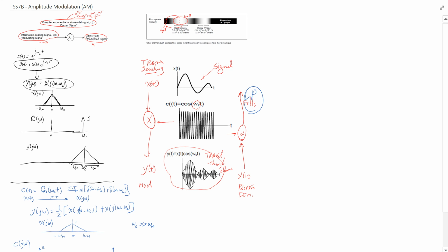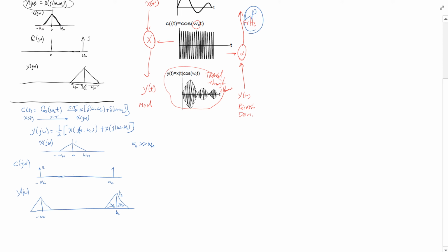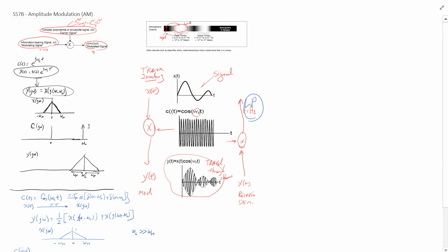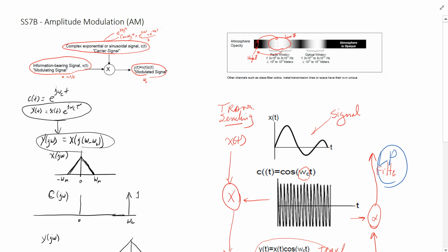The goal is to take a frequency and move it in the frequency spectrum to where it's going to go through. For example, for an AM station, a human voice is being transmitted, music and things like that. That's 20 kilohertz. So they take that 0 to 20 kilohertz and put a carrier frequency somewhere between 0.5 megahertz and 2 megahertz.